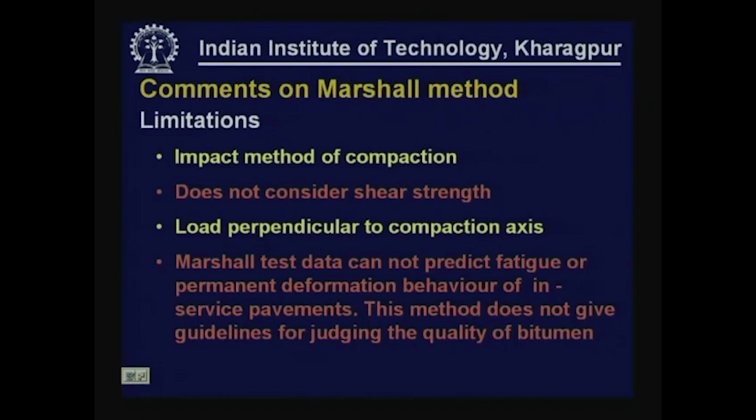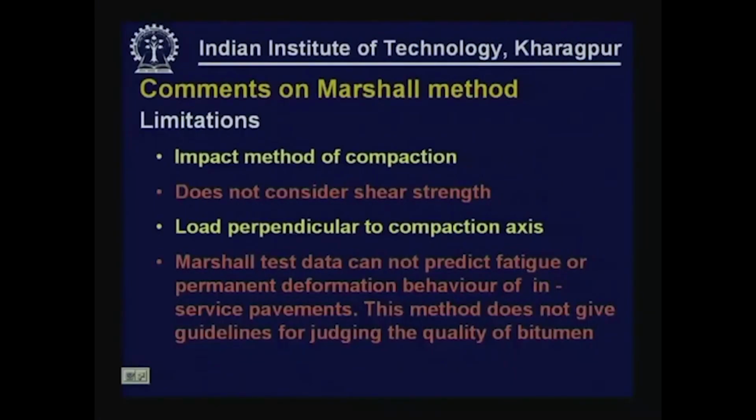It does not consider the shear strength in the method of testing the specimen, which is diametrical loading. It does not take into account the shear strength of the specimen, because the load is perpendicular to the compaction axis. Marshall test data cannot normally predict fatigue and permanent deformation behavior of in-service pavements. This method also does not give proper guidelines for selecting the quality of bitumen.